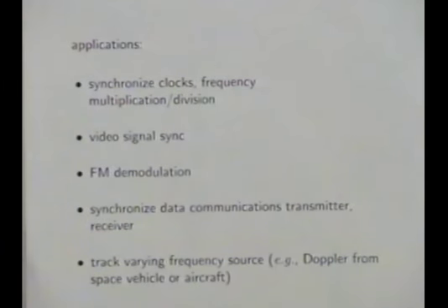One is to synchronize clocks. So if you have two devices talking to each other over a communication link, their clocks are actually pretty accurate. I mean, crystals these days are very accurate. They're accurate certainly to a part in 10 to the 8 or something like that. But in fact, they drift. And if it's not a very expensive crystal, it could be off in the 4th digit or something. So if one guy thinks he's transmitting a communication signal at 1.000 megahertz, and the other guy thinks he's receiving it at 1.0, but they're off a little bit, you can easily imagine that things will eventually get messed up, and you'll be reading the wrong bit and all that sort of stuff. So the way that's done is you have a phase lock loop that locks the two clocks together. So that's the way you do that.